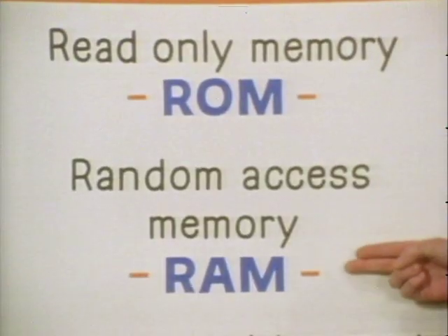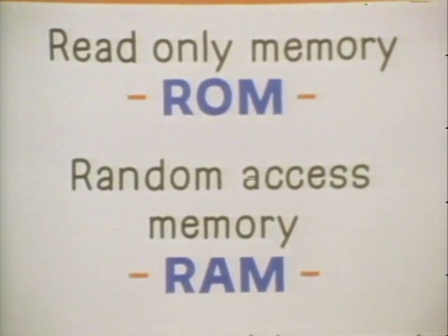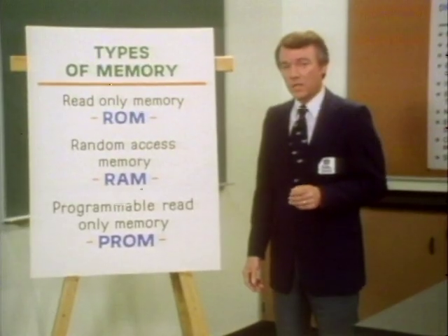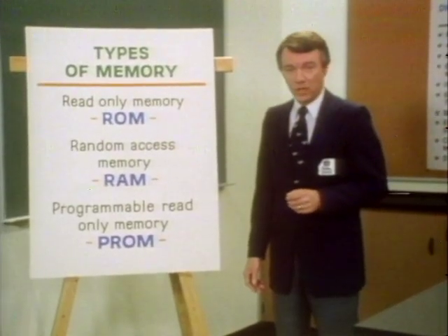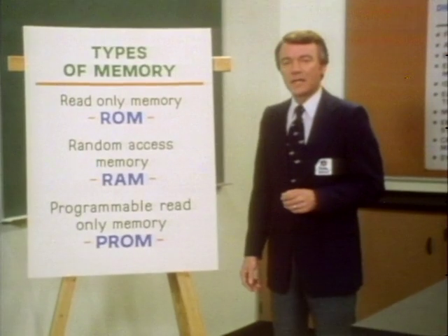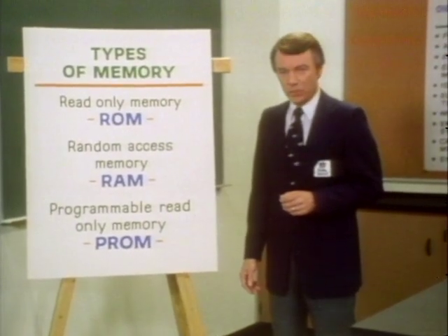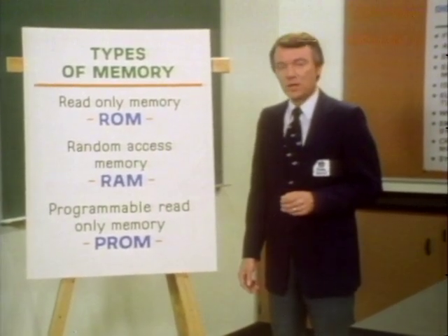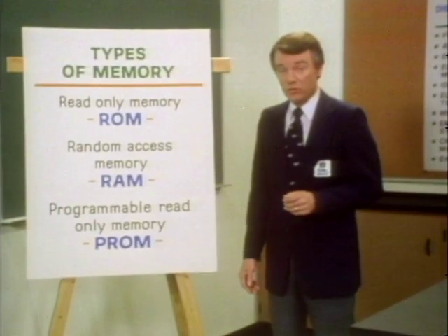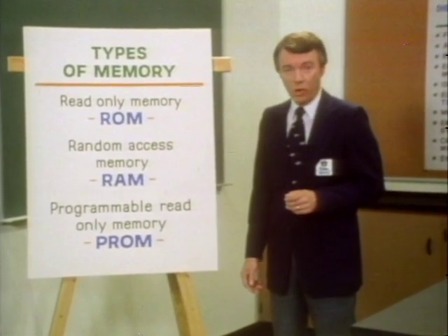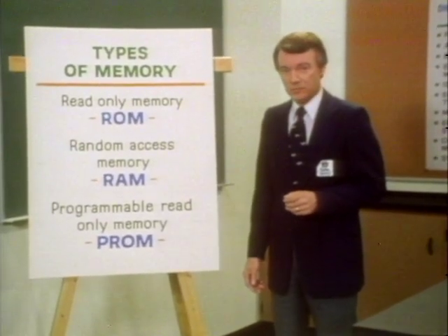Random access memory, RAM, is what is called the scratch pad memory for the CPU. Information can be read into or out of RAM, such as engine sensor information, diagnostic codes, and DFI operation calculations. These are stored in RAM temporarily, so if battery voltage is lost, all the information in RAM is lost.